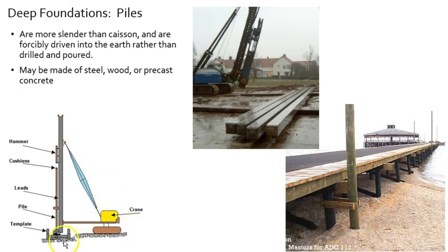Here's the crane. The template is to guide the pile down, essentially. There's the pile right there, and then a cushion at the top of it, and then the hammer drops and drives the pile forcibly into the earth. Here are some concrete piles awaiting placement.